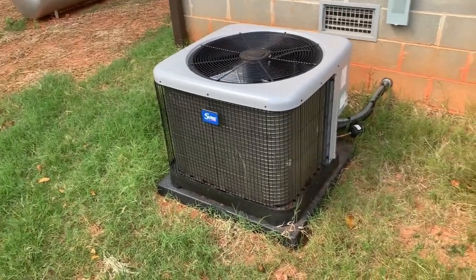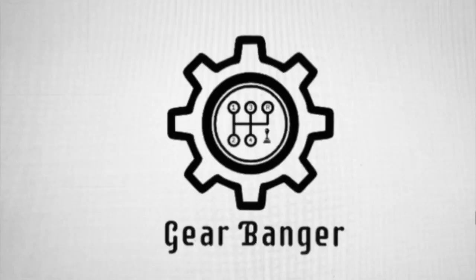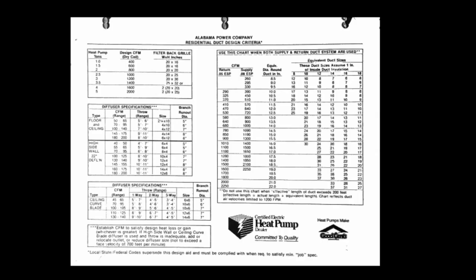So let's talk about the HVAC system. First off, we're going to talk about the calculations on the system itself. The load calculation on it is 27,000 BTU. We went with a 2.5 ton unit. For a 2.5 ton unit, the optimal airflow is 400 cubic feet of air per ton, so that's 1,000 cubic feet per minute. What the house ended up needing is 1,035 cubic feet of air per minute.